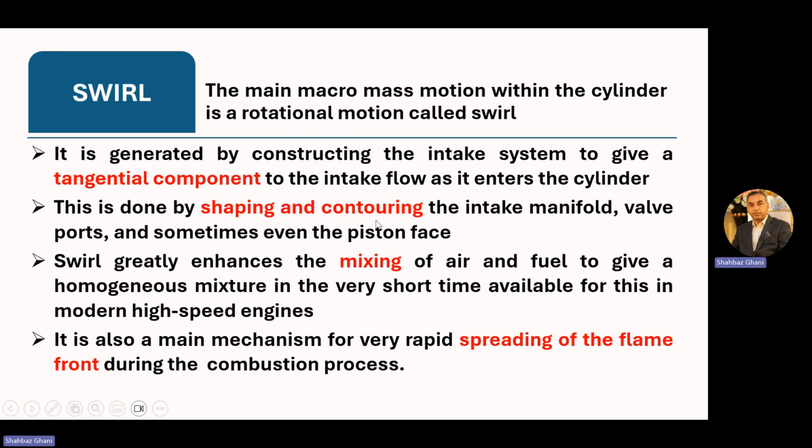This is done by shaping and contouring the intake manifold. We achieve this swirl motion by shaping and contouring the intake manifold, valves, ports, and sometimes even the piston face. The top of the piston face is sometimes made so that we get a swirl motion of the air-fuel mixture which is coming in. Swirl greatly enhances the mixing of the air and fuel to give a homogeneous mixture in a very short time available for this in modern high-speed engines.